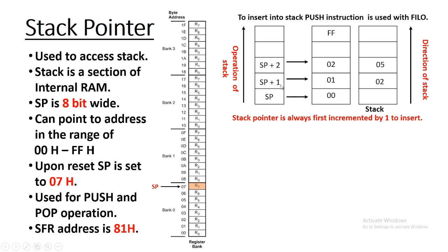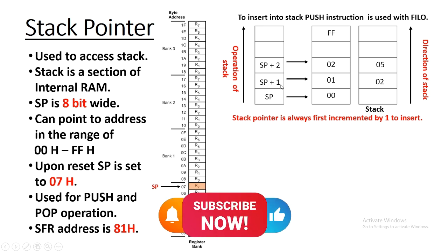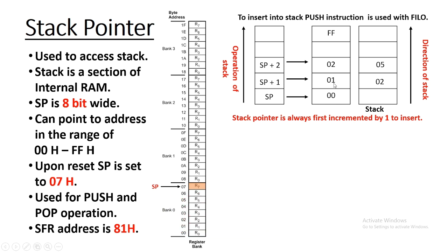SP is incremented by 1 and then data is stored. The location which is pointed to by the stack pointer is known as the top of the stack. So now the top of the stack is 01. Suppose again I want to push any data onto the stack, the SP, the top of stack, would be incremented and then the next data would be stored.